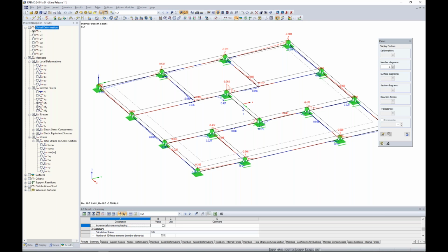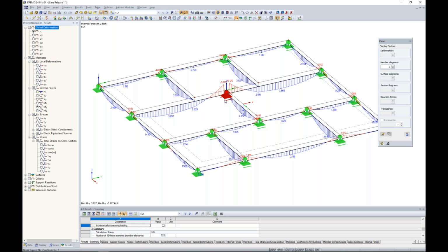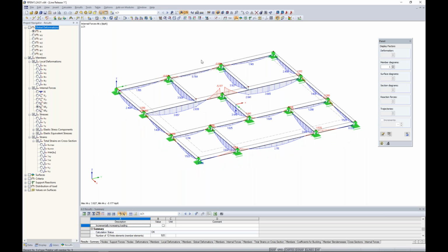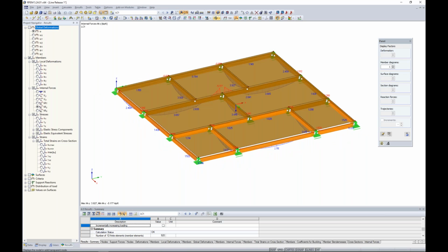The other thing is if we take a look at the bending moment, these are supposed to be simply supported member elements here with pin releases, and we have extremely high negative bending at one end. Now it eventually goes back to 0, but we definitely don't want to see such high negative bending either. The problem is that we have defined this composite type behavior and everything is rigidly connected, when in reality we want partially composite behavior because of the connection between the CLT floor and the glulam member. So how can we take that into consideration?